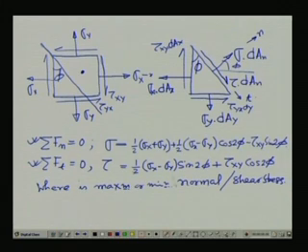Where is the maximum normal and oblique shear stress? That means which is the location we would like to find out. For that, with simple mathematics, we can just take the derivative of the normal stress and the shear stress with respect to the angle, and thereby we get the required relationship. So if we find this relationship, then d sigma n by d phi equals